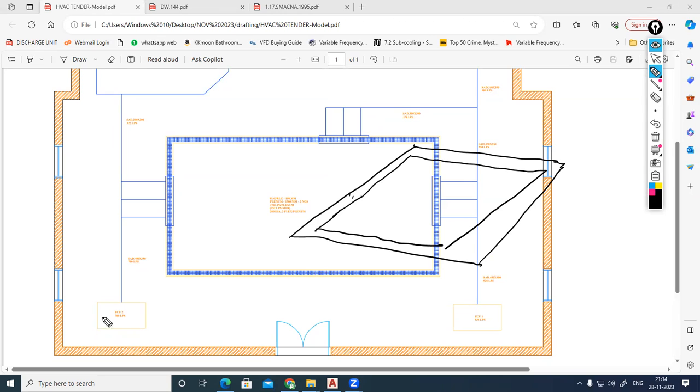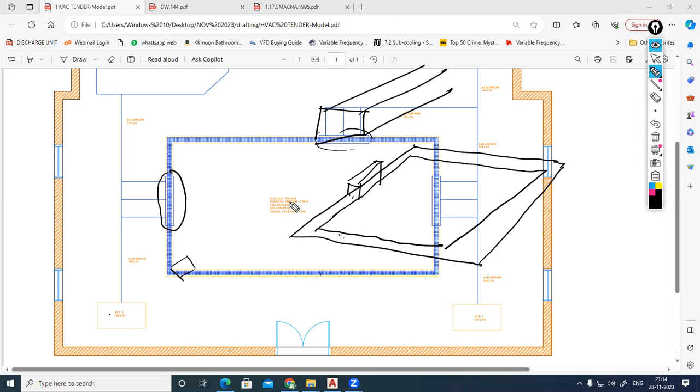Now, from here we have a machine. Okay, this is our machine. How will we provide it? Here you can see we have this one, a box. This box is called a plenum box. There we have, here we have, here we have. Meaning you might have a duct on the top side. This grill will be fixed on the false ceiling. And above this grill, we will be placing a linear box. This linear box has a length of 1500 millimeter, meaning a length of 1.5 meter.